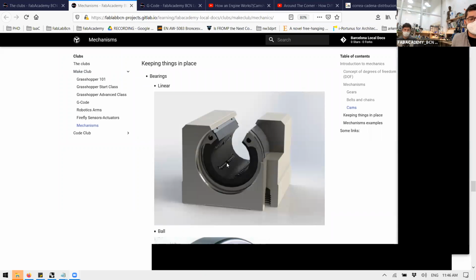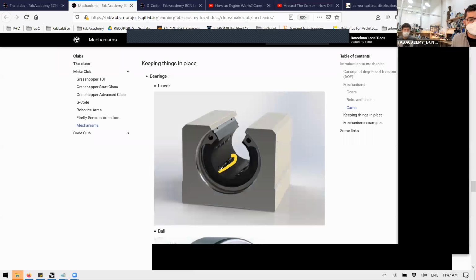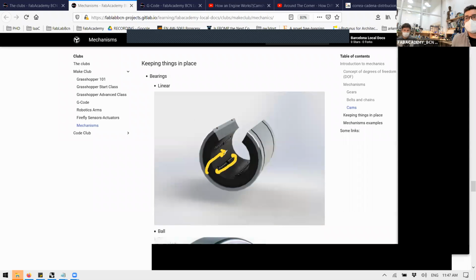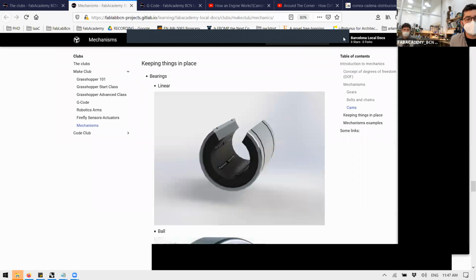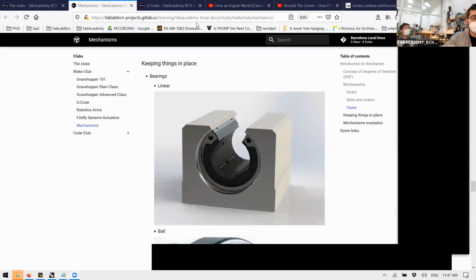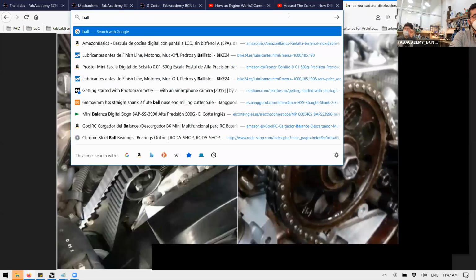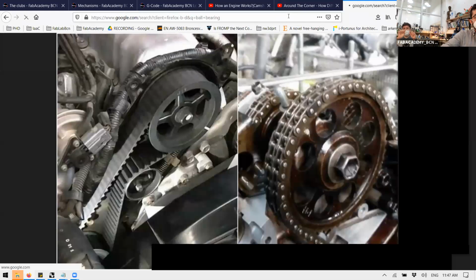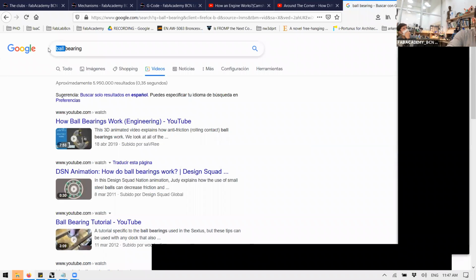So basically, when the first ball that is here is moving to here, inside there is a loop back for the balls. So actually, the design of this for the size is quite complex. The balls are moving. They not only rotate, but they also move. They have a small channel, and they push one another, and they go linear.